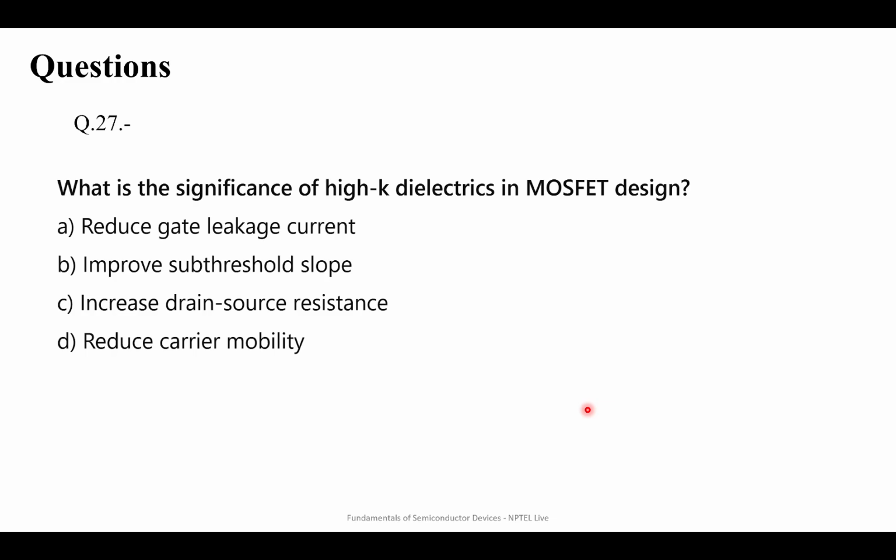So, what is the significance of high K dielectrics in MOSFET design? Reduces gate leakage current, improves subthreshold slope, increases drain source resistance, reduces carrier mobility.